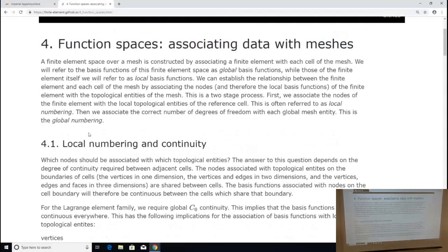Thus far, we've done all the legwork to set up finite elements on one reference element. We get given reference elements, we can put nodes down on reference elements, we can make a polynomial basis on a reference element, which is what the Vandermonde matrix more or less does, and we can put those two things together to get the finite element basis on an element, and we can evaluate it. So we can do individual elements.